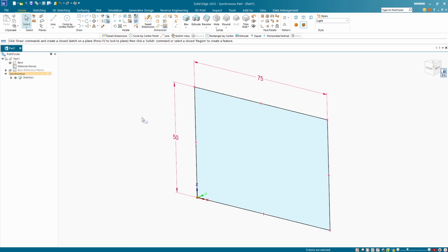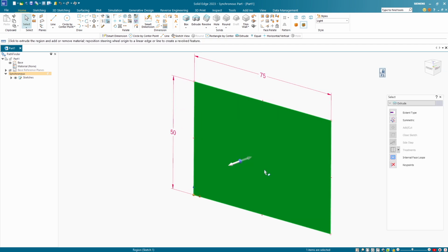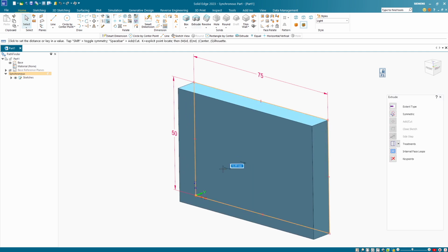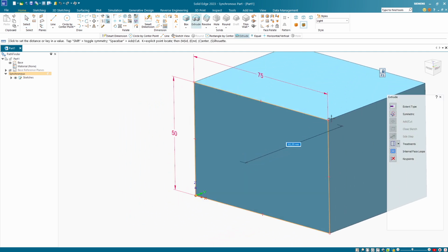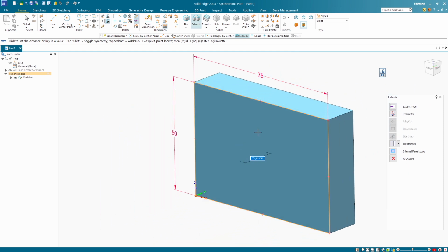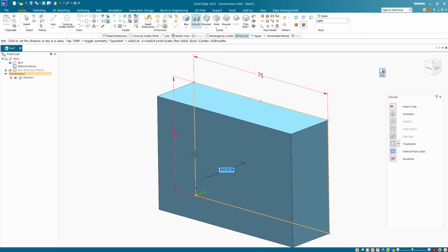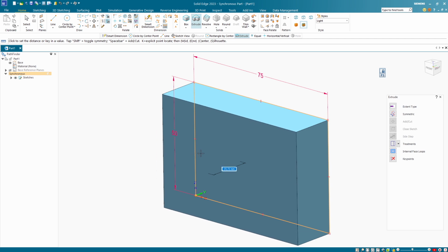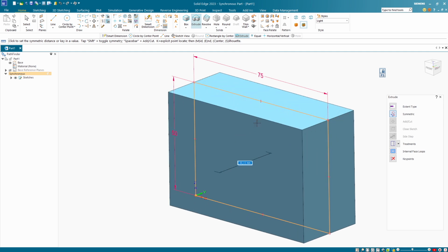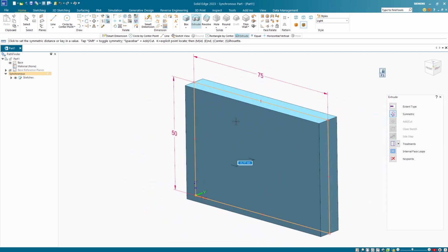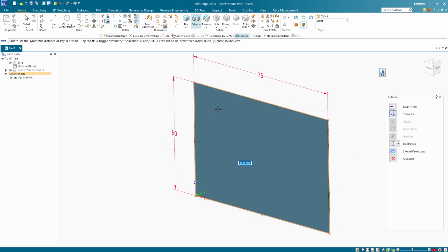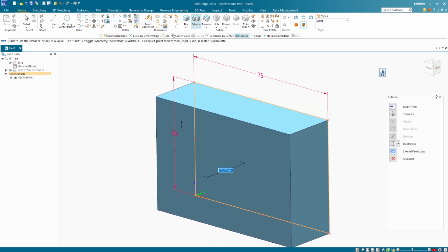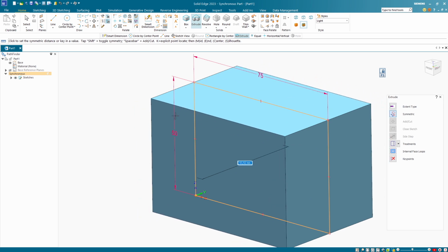And all you need to do is now just click this region here. Left click, and you will see it turns green. We got these two handles here. And now let's try and click this handle. And as you see, you can extrude in both directions. If you press the Shift key just once, I just press once the Shift key on the keyboard, Shift, you now see that the extrusion is symmetrical. Okay, and you can toggle this symmetric extrusion simply by clicking Shift.